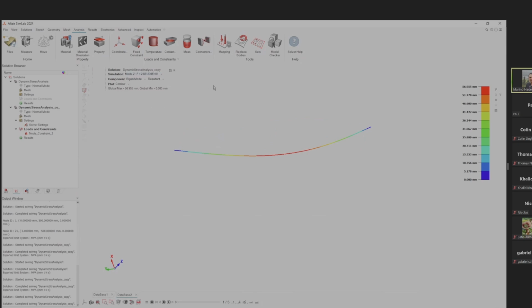Yes, and the second mode is the same magnitude but different frequencies because they are in different directions. This is something I like to emphasize to the students, to realize what they're doing. That's just because it's symmetrical. You'll get first order bending, and then it looks like another first order bending. And then a lot of times you'll get second order, first order torsion.